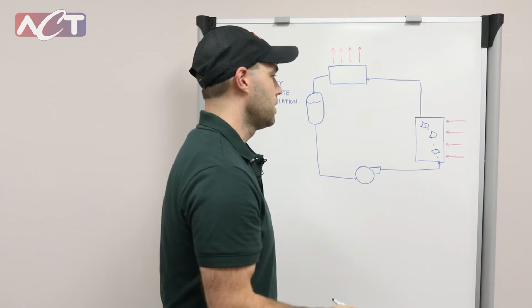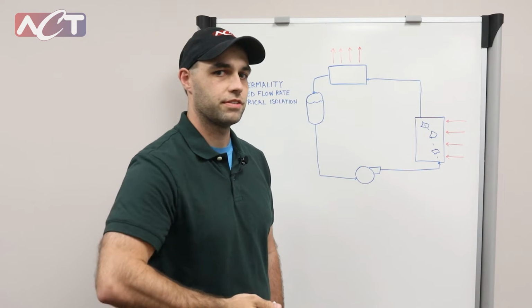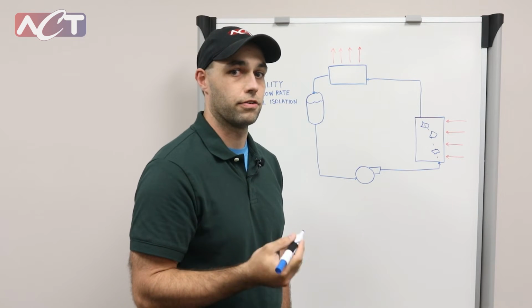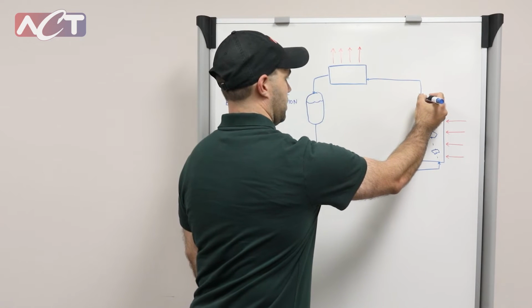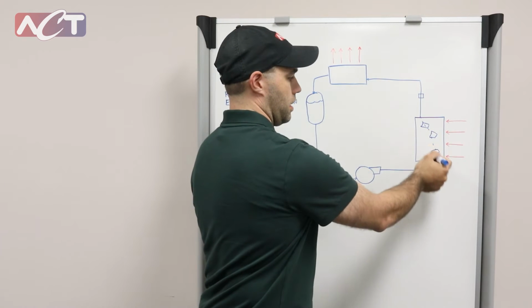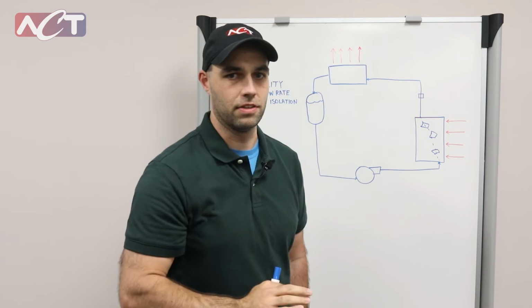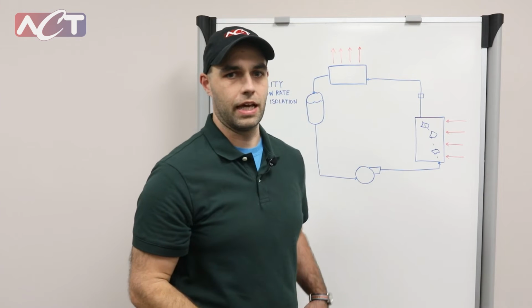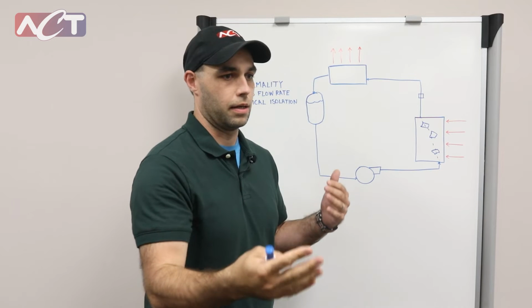at the beginning. In addition to that, with isothermality, you can control the temperature very well because the temperature that you're boiling at is a function of pressure. And so you can actually add a device here that would regulate the pressure here without regard to what's happening in the rest of the loop. And so the pressure would be there, so the temperature that you're boiling at remains constant and allows you to have isothermality over time as well as space.